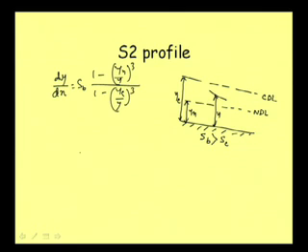From this equation it is clear that if it is in zone 2 and it is a steep slope, then your critical depth is greater than y and normal depth is less than y. So, if one ratio is positive, then the other ratio is negative. And if it is a mild slope profile, then your normal depth will be greater than the depth y, and the critical depth will be less than the depth y.